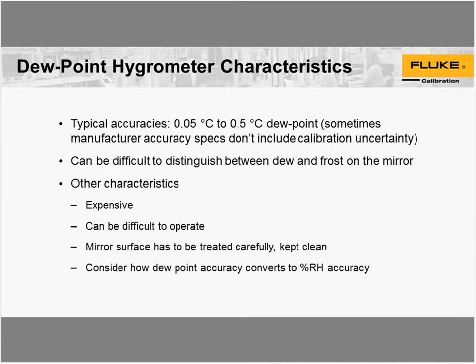Okay, other characteristics: usually because it's a complicated instrument, they're fairly expensive, and it can be very difficult to operate. They are finicky, in that the mirror has to be clean, but then it's possible that it may get too clean for some chilled mirrors. They're sensitive if the mirror is too clean, and so there's definitely some art to measurement of dew point with a chilled mirror.